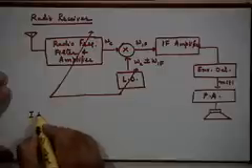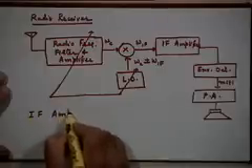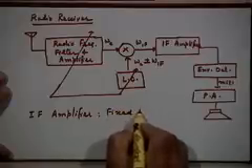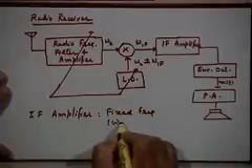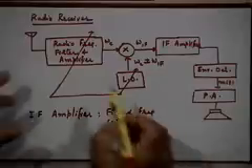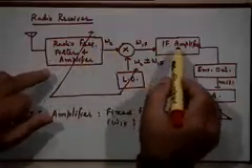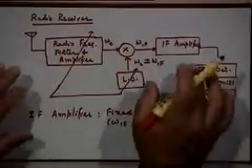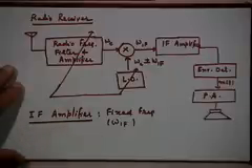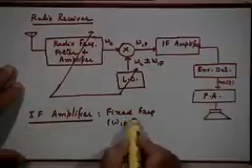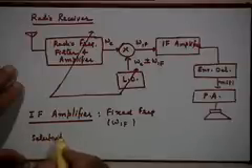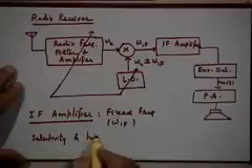The IF amplifier? Yes. Basically what we are saying is, because the IF amplifier is at a fixed frequency, what is the fixed frequency? Omega IF, right. No matter what the incoming signal frequency is, the same signal is now available at omega IF, right. It's much easier to design an amplifier of fixed frequency with the properties that you want, namely high selectivity and high sensitivity.